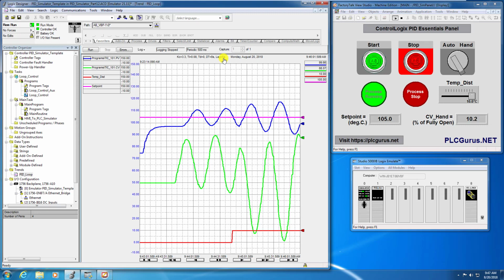If your dead time over lag time is less than 1, you should be able to control it. If your dead time over lag time is greater than 1, you're going to have some problems controlling that process, okay? And you need to employ some tactics in order to get the dead time lower, all right? I hope that's clear.